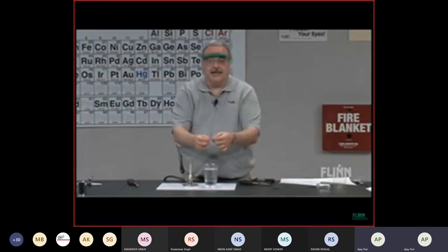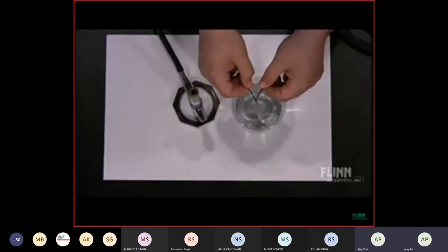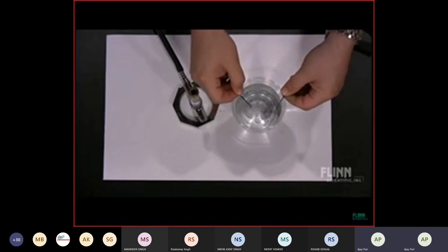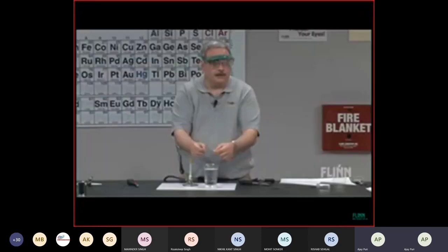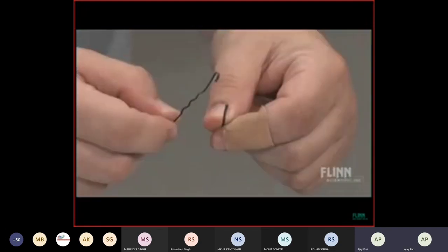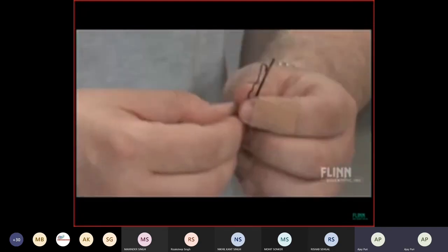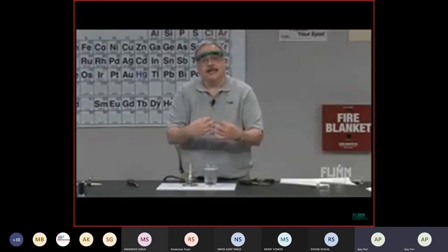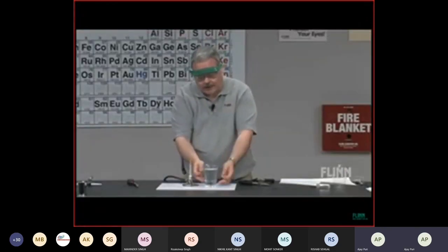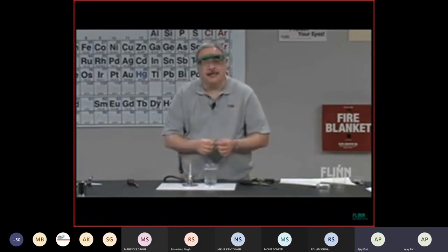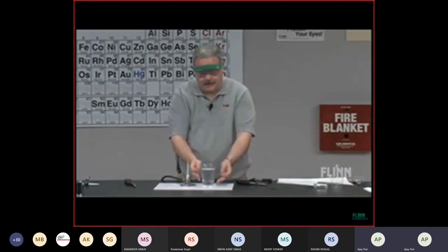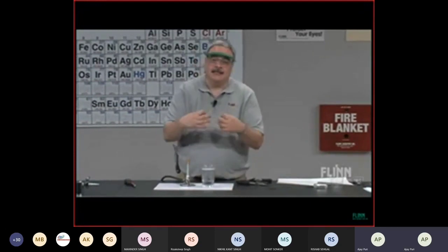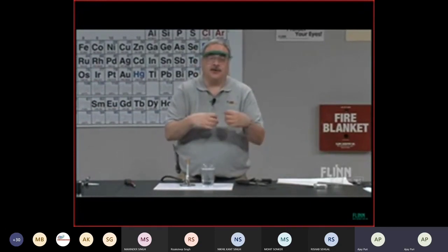Let's look at this and see what happens. We've heated it to red hot, we've cooled it quickly, and let's see what happens. I don't know if you could hear it, but it was very brittle. And so what we've done is change the crystalline structure in a situation where it was not able to, as we cooled it, contain as much carbon. So what we were able to see here is some of that carbon precipitating as iron carbides. And so we're pulling out some of that carbon since the new crystalline structure can't hold it.